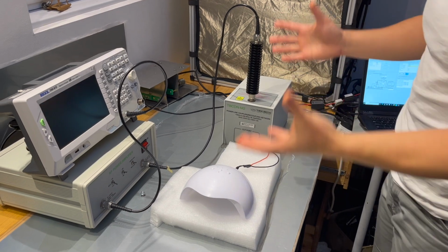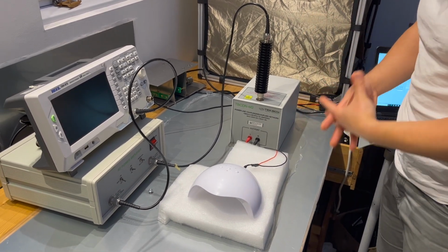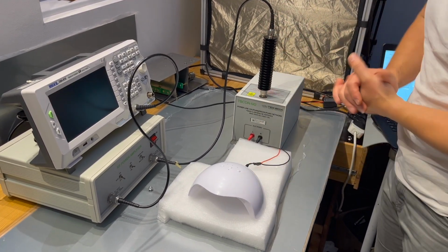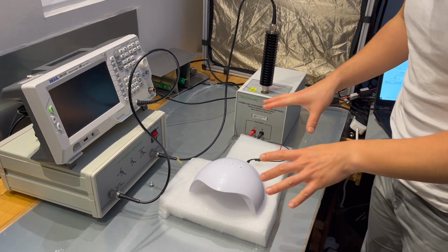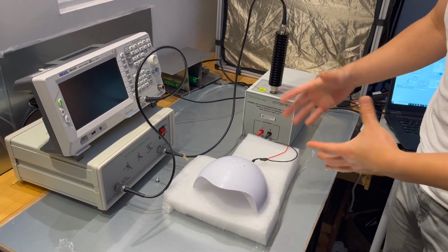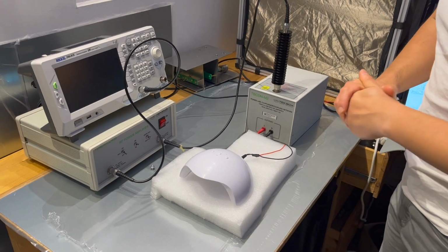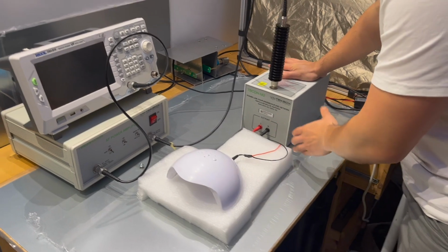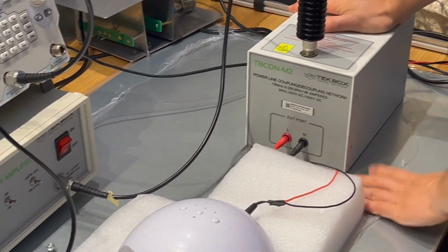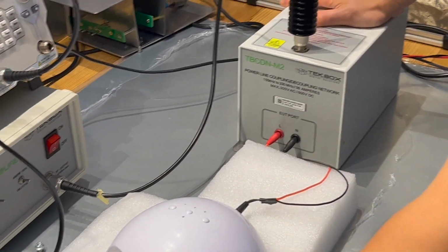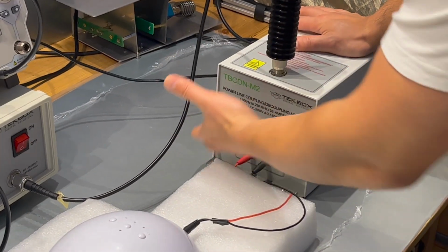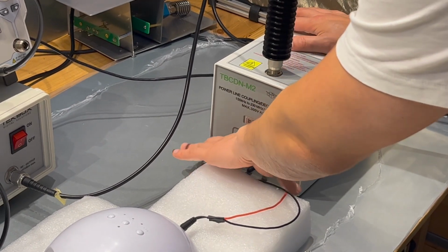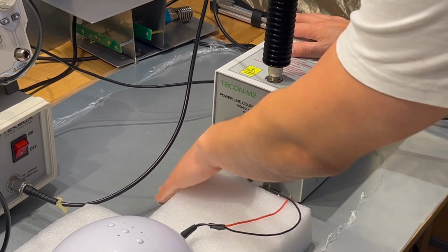As you can see, now we have disassembled the calibration setup and set up the proper conducted immunity pre-compliance test setup. We have already demonstrated this setup in a separate video, so you can watch that video as well. For this video, the most important thing is that the CDN needs to be bonded really well to the test ground plane, as we explained, because this coupling and decoupling is very important. So the CDN needs to be electrically bonded well to the test ground plane.